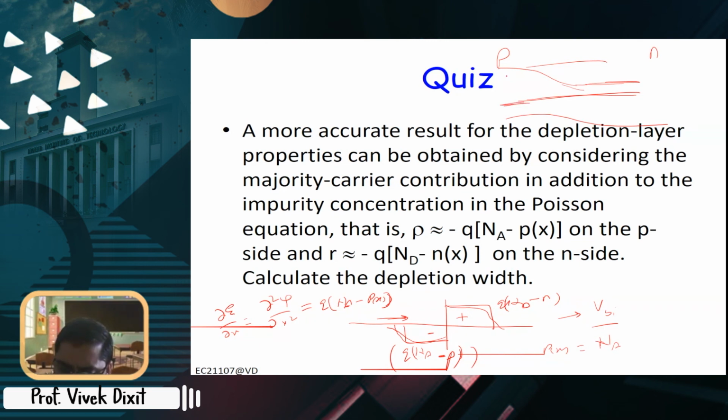So the potential difference, right? So here the concentration is Na basically, right? Now as you move away, this is changing. So this potential is changing. So now the gap between the Fermi level and the conduction band is changed by this potential Q psi, right? So the hole concentration will decrease by exponential of minus Q psi, right? So you can write your P is basically Na times exponential of minus psi, and this coefficient becomes Q by KT, right? So if you substitute it, you can try this one, and please try to obtain the expression for the built-in potential in this case.